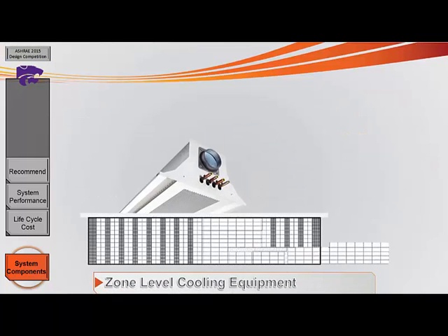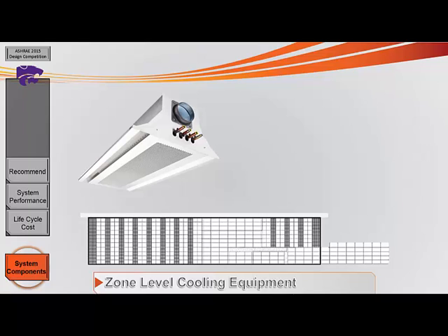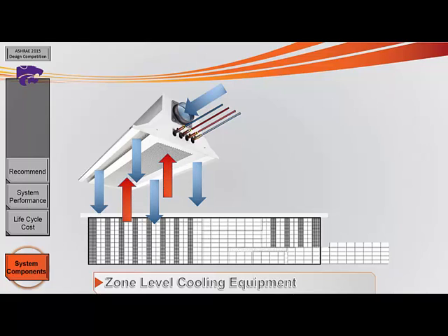Active chill beams will be used everywhere other than the workshop areas. This is because of the dust that could clog and decrease the performance of the chill beams. Active chill beams condition the space by passing dry air from the dedicated outside air unit over a chilled water coil. This air then drops into the space. Chilled beams take advantage of warm air rising in the space through induction to pass back over the coil, to be cooled and drop back into the space.